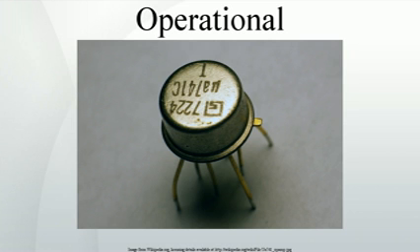As a simple example, if Vin equals 1V and RF equals RG, Vout will be 2V, exactly the amount required to keep V at 1V. Because of the feedback provided by the RF, RG network, this is a closed-loop circuit. Another way to analyze this circuit proceeds by making the following, usually valid, assumptions.